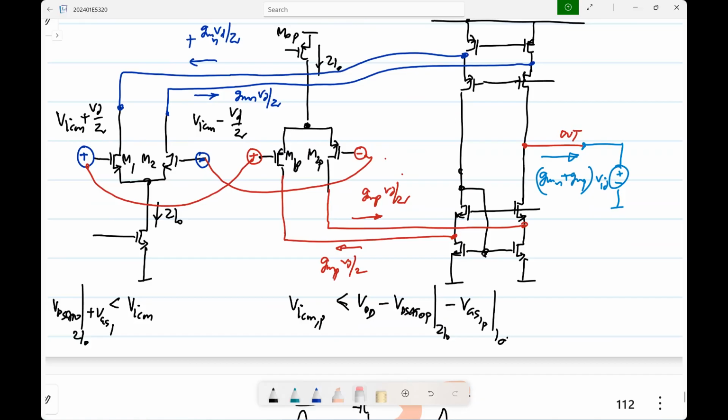Fully differential is what you do in most cases on an IC. And the feed forward op amps are typically used only on ICs. You don't make them with discrete components anyhow. So it is possible, but anyway, I won't spend time on that. So I will discuss only the Miller type multi-stage op amps, in the single-ended version.